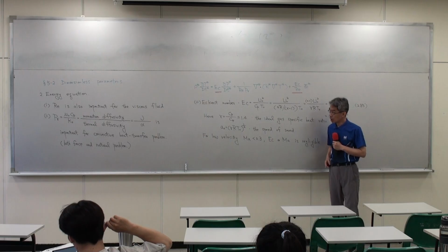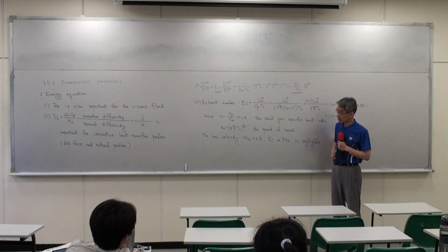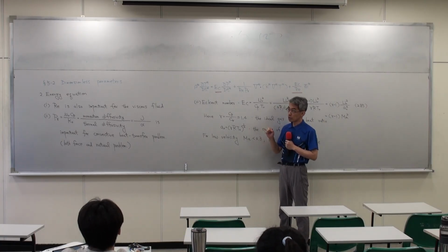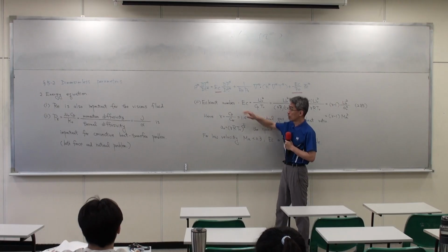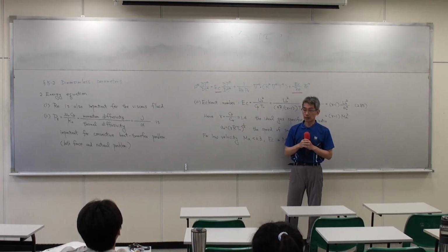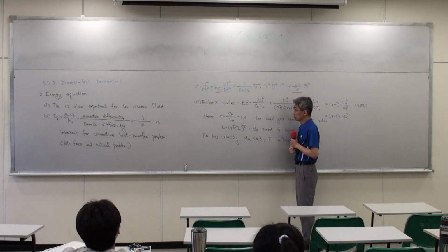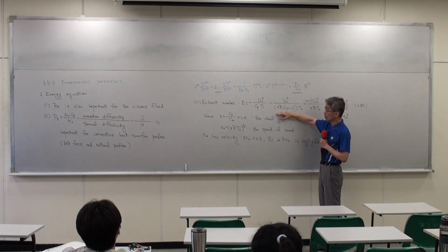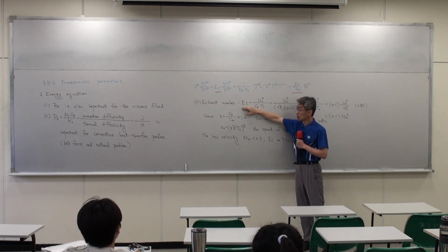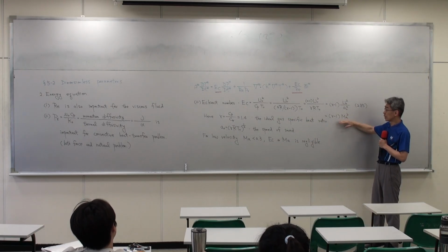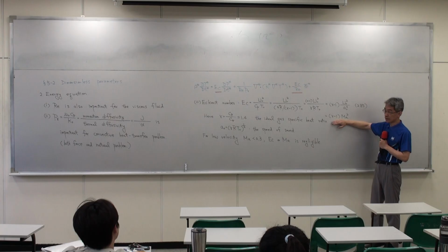So far, any questions about the energy equation we talked about? I think previously, in most of the cases, mechanical energy didn't contribute too much to the total energy. And we can also convert the Eckert number into the Mach number. The Eckert number is the same as the Mach number after you use the ideal gas equation to convert between them.